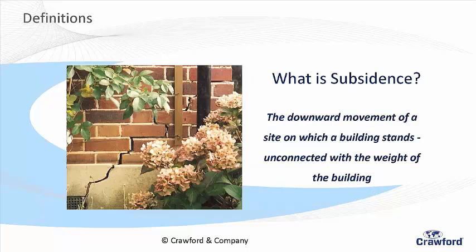Yeah. So the definition of subsidence, very quickly. We say downward movement of the site on which the building stands. When the site moves down, the masonry, the structure, drops down after it. And you end up with a rotational movement and a wider crack at the top and at the bottom. And a textbook crack I found. Very late to you, but there you go.